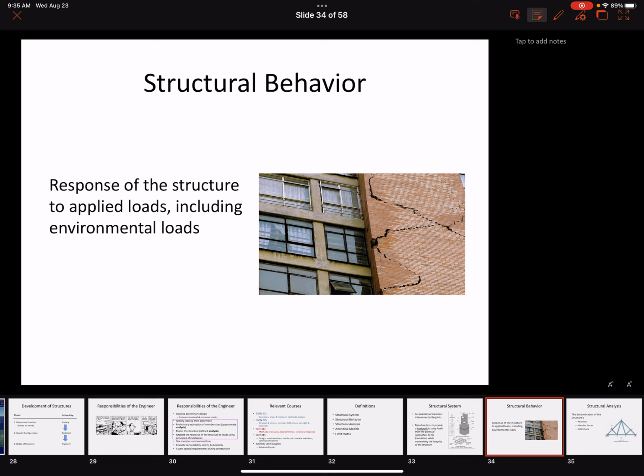We're going to talk about all of those next week. But my point is that behind that brick facade is the real structure that's responsible for transferring those forces safely to the foundation. So the cracking that you see in the brick is not necessarily a sign that the structure is going to fall down and crumble. But it is a significant red flag, so this would need to be inspected thoroughly before it was flagged as safe for reentry.